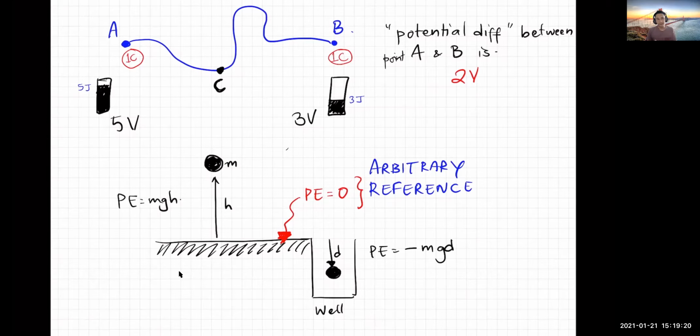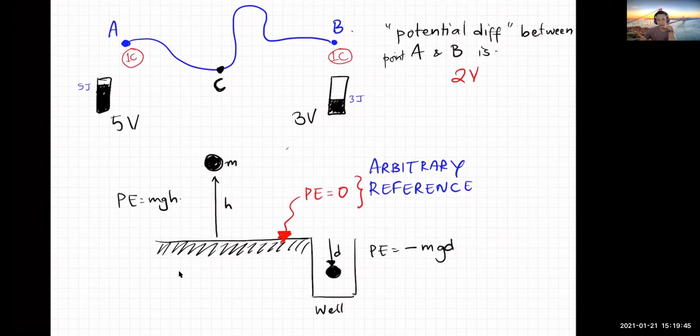There might be some difference between a reference and a ground, for larger circuits. When we say ground, it technically means it's actually grounded to the earth, but a reference can be something other than that as well. Okay? But for a beginner's understanding, just understand that a reference ground is a point on the circuit where we say that the potential is zero or the voltage is zero, and then we can measure other node voltages with that reference. Okay.